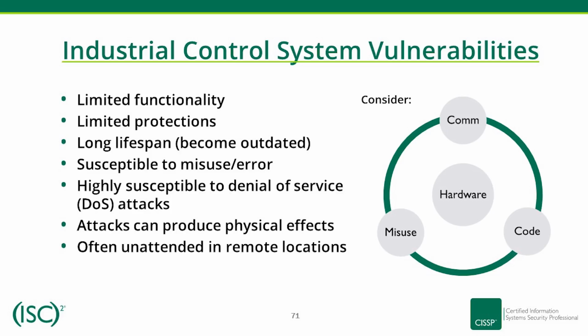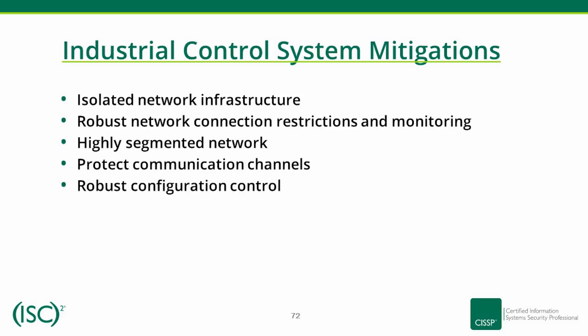Highly susceptible to denial of service, DOS, attacks. Attacks can produce physical effects. Often unintended in remote locations. Consider isolated network infrastructure. Robust network connection restrictions and monitoring. Highly segmented network. Protect communication channels.